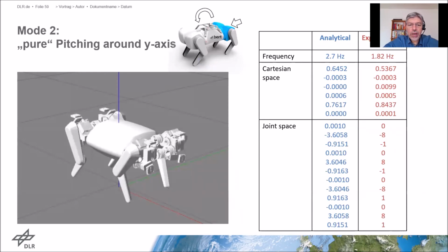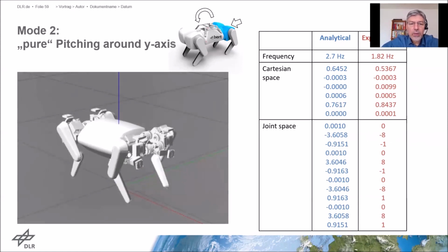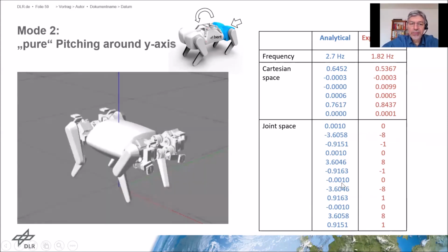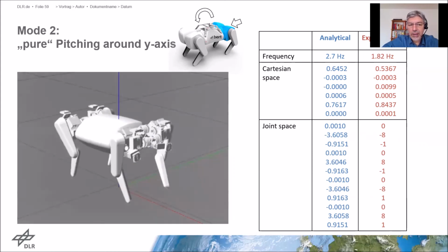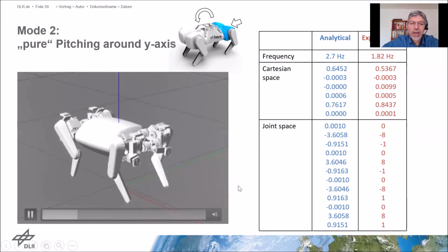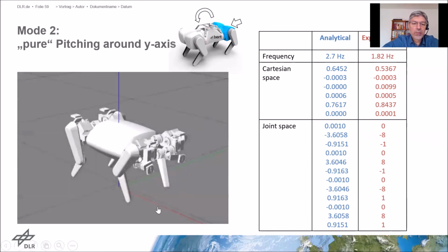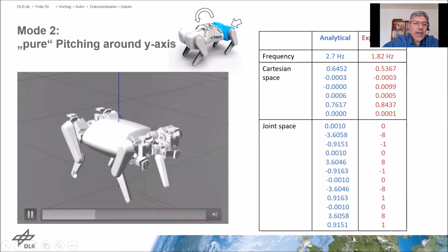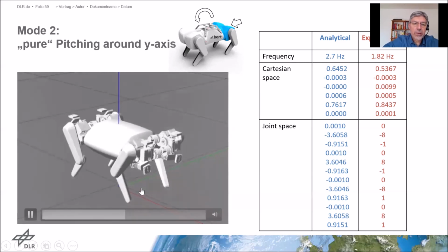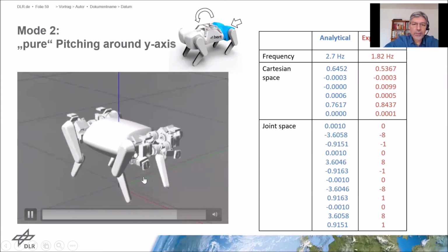What I would like to show you now is a design of a quadruped which we are just assembling right now, and where we analyze the linear modes first of all, and then also their nonlinear mode extension, which we excite by a controller I will present in a minute. And we see that those intrinsic modes are very similar to some biological motions. Just a few mentions for the type of the model. In this case, we attach the legs to the ground, so the feet are connected with ball joints to the ground, such that the overall system has only 6 degrees of freedom. So you expect to have 6 modes.